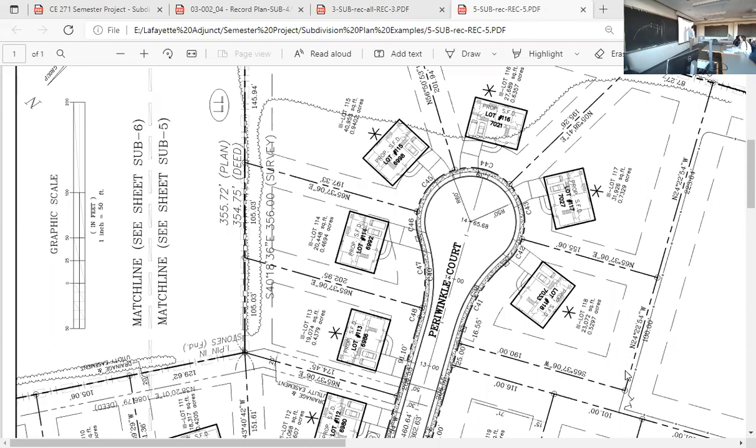All you need to show is the building and that it fits in your building restriction. Again, this one labels the lot right on the lot. You can do a table. This one, the sidewalk is drawn and hatched. I want you to draw the sidewalk. Do I want you to hatch the sidewalk? You're doing the drafting and engineering. Do a drawing that looks good.